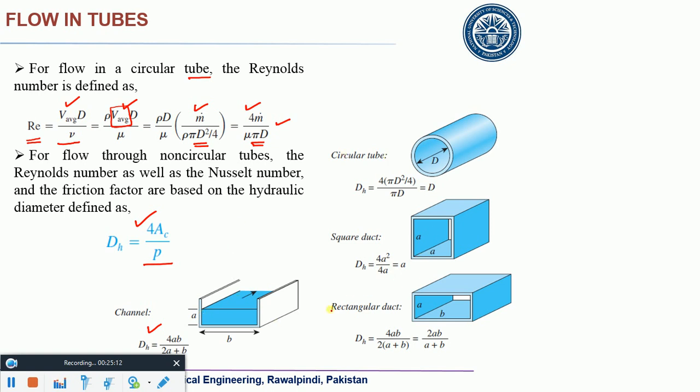So in all of those figures or tables, you may see the relationship for hydraulic diameters. You just need to use the appropriate diameter and the appropriate V average and find the Reynolds number. But this is not very straightforward. Finding the Reynolds number in the case of internal flows is a little tricky, right?